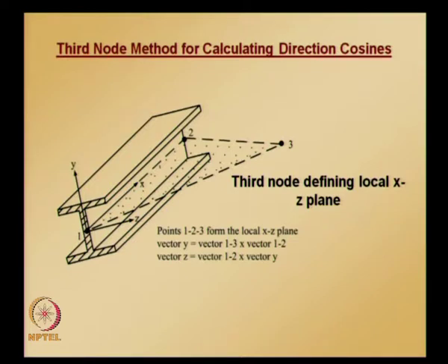For each element, global displacements can be transformed into the local displacements, because when we want to calculate these axial forces, moments and shear, whatever, when we solve the global equation system we get global displacements in the global coordinate system.